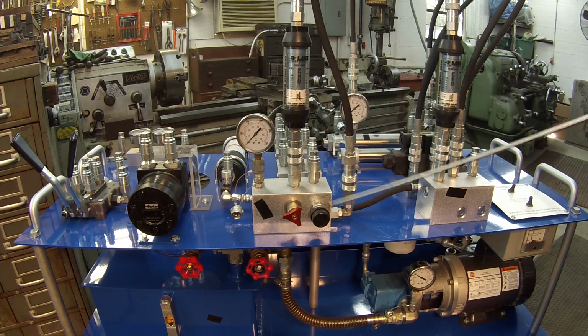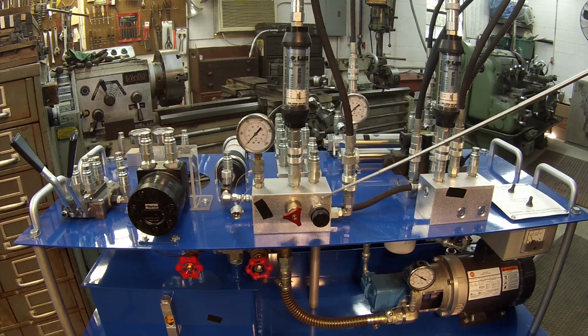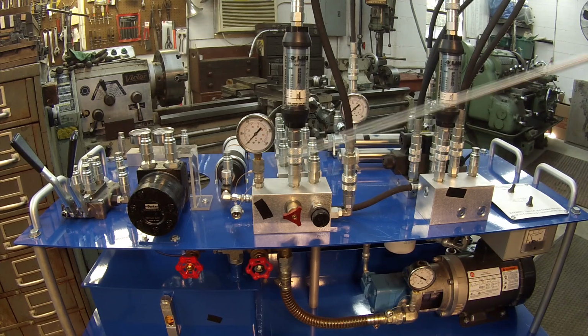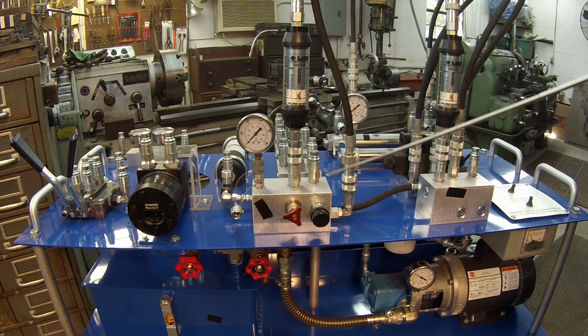The biggest failure that I have with these relief valves is the wrong pressure range. If I'm going to operate my hydraulic system at, say, 1500 psi, and I get a relief valve that goes from 0 to 800 psi, what's going to happen is every time you turn that system on, your fluid's going to dump over your relief valve, and nothing's ever going to happen out here. So it's very important to make sure your spring range is correct on your relief valve.